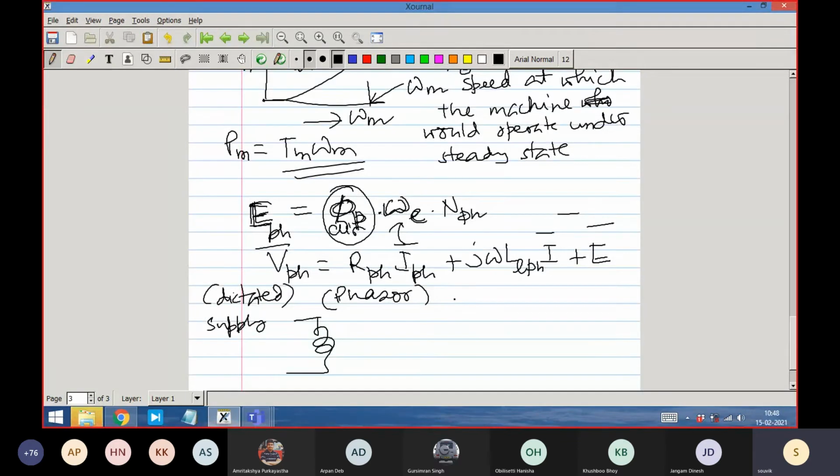I say that the coil R phase is equal to 0. Let me simplify that LL phase equal to 0. These are simplifications I will do. Because of leakage inductance, I can easily think that the machine is ideally constructed, no leakage. I can think that. And qualitatively, these drops are very small.